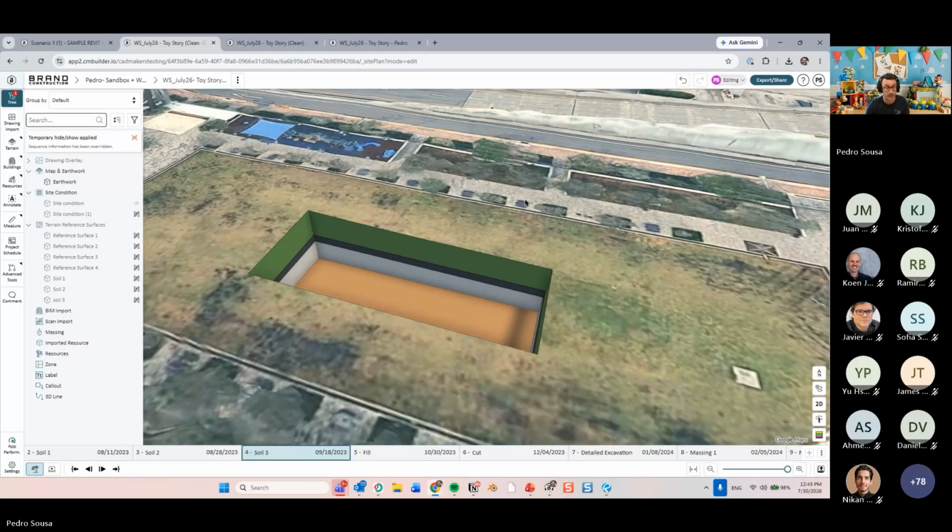There is a way to do that. I haven't yet completely cracked that way, but you would need to export a CSV table containing X, Y, and Z coordinates for those points that will be geolocated. And when you import that CSV, it will represent the points and create the surface in the correct spot over here.